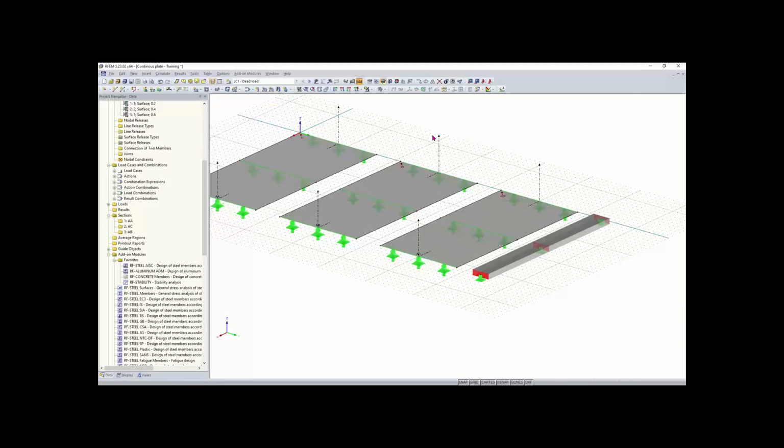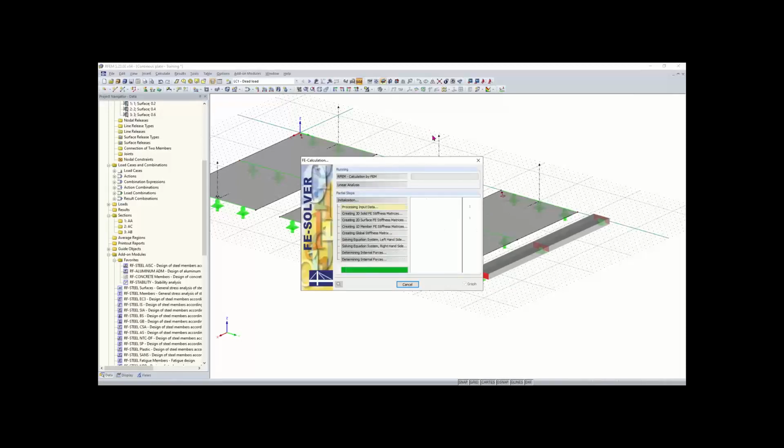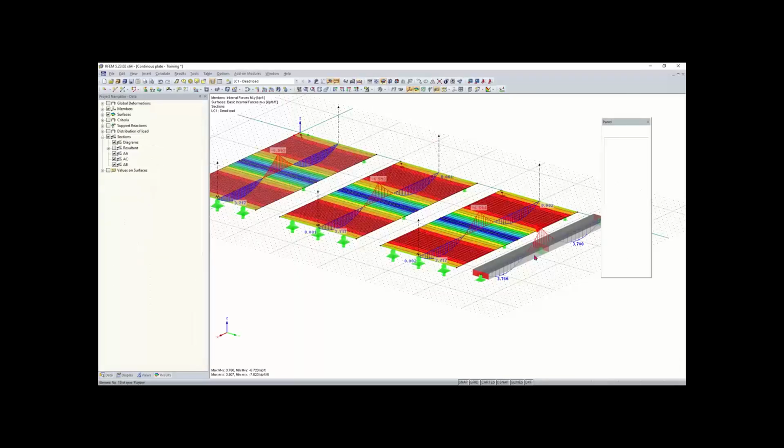And then once I recalculate, you'll see that the results are going to change just a little bit, and the results are mostly going to be the bending moments, because instead of RFEM taking into consideration shear stiffness, it's just going to assume an infinite rigid stiffness for the shear. And I'll get into that just in a little bit. So basically, this is because the methods used in school, like I said, assume an infinite shear stiffness, when in reality there are some shear deformations for bending. So just keep this in mind when comparing hand calculations of deformations with RFEM.